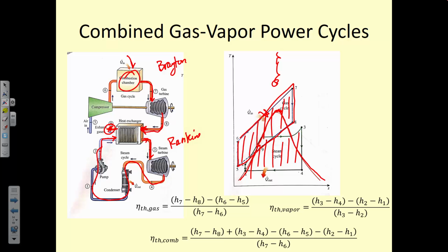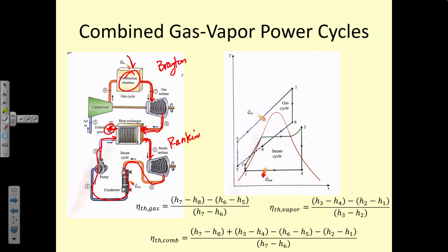I have a crazy question. If 8 to 9 on the Brayton is the heat rejection, is the area under the line from 8 to 9 equivalent to the area under the Rankine cycle? Since that's the heat input into the Rankine cycle. Like this area here? Is that equivalent to the area under 2 to 3? In an ideal cycle, it should be.